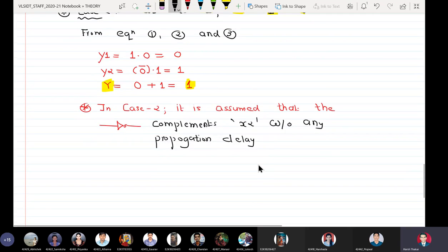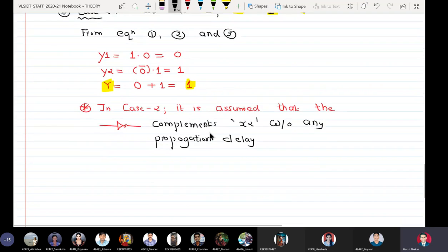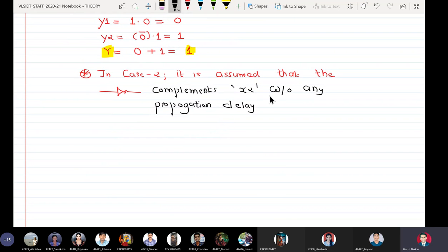But if you read the datasheet of any logic family, it clearly mentions that a logic gate always has a non-zero propagation delay. If you take the TTL logic family of 20-25 years ago, the standard propagation delay was 10 nanoseconds. Naturally, because transistors have become more efficient and faster, propagation delay has reduced, but still it is not zero.